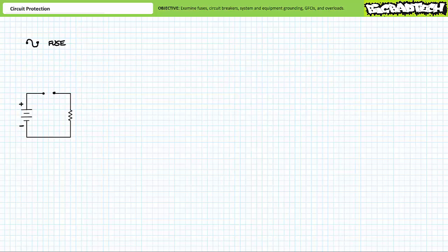When subjected to current above the rated value, a fast blow fuse melts and opens rather quickly, whereas a slow-blow fuse would take an appreciable amount of time to melt and open. A slow-blow fuse would allow a temporary surge of current, however would open if current remained in this elevated state for any length of time.